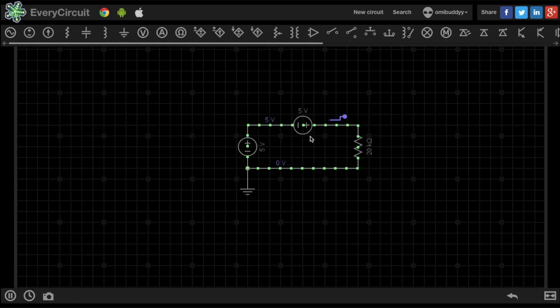Now let's put back the voltage source. As seen before, 500 microamps of current is flowing through the input voltage source. The input voltage is actually a voltage signal which we want to amplify. This voltage signal could have been generated using some transducer. The transducer is similar to a voltage source, and hence there will be a limit on how much current you might want to pass through the transducer based on its type. In the best case, we don't want to take any current from the voltage transducer, which will make sure the input signal is not affected.